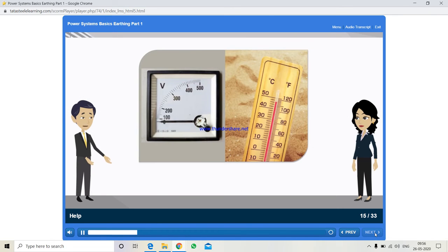Yes. So firstly, the size of ECC required is determined by consideration of voltage drop and temperature rise. It is recommended that under fault condition, the drop in ECC should not exceed 32 volts.